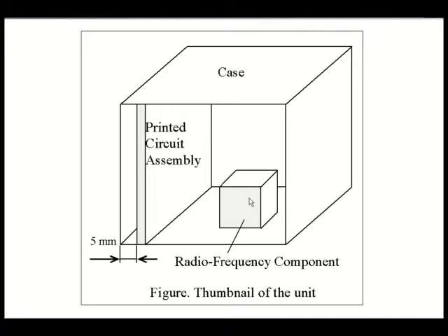In the right part of the unit, at the bottom of the case, the transformer is fixed, dissipating thermal power of 4 watt. Its sizes are length 30 mm, width 30 mm, height 50. Lubricant is used while fastening the transformer. Ambient temperature around the unit is equal to 30 degrees.